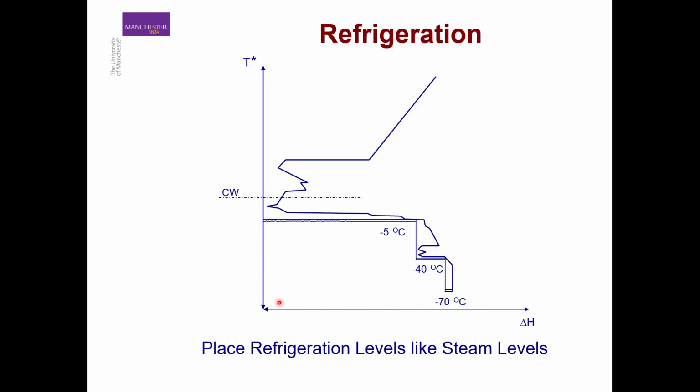So we have to always make a choice in terms of complexity and in terms of the cost. The total amount of refrigeration that is required in terms of QC min, for example, the minimum utility requirement, would be a sum of these three utilities, the one with -5 degrees centigrade, -40 degrees centigrade, and the -70 degrees centigrade.